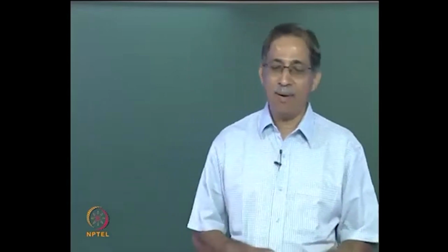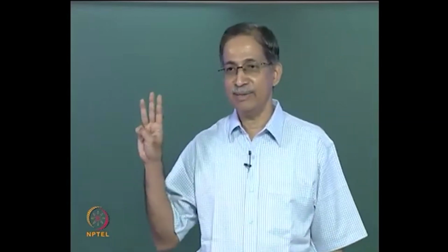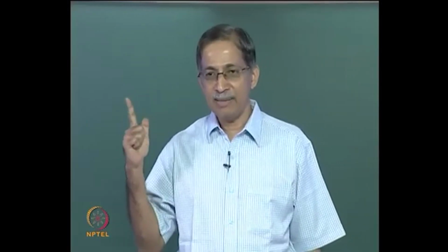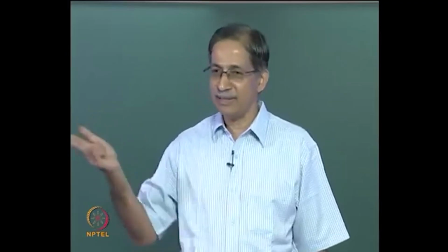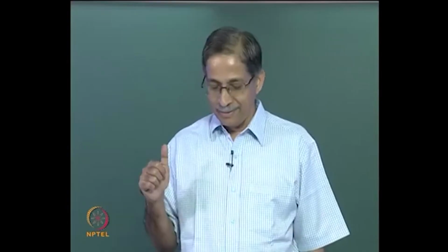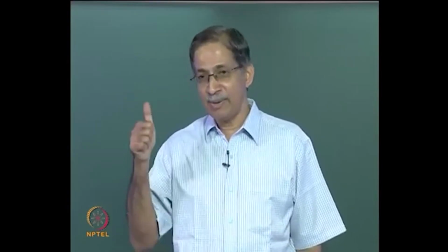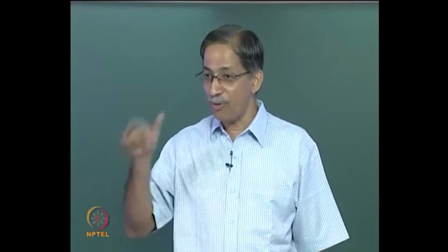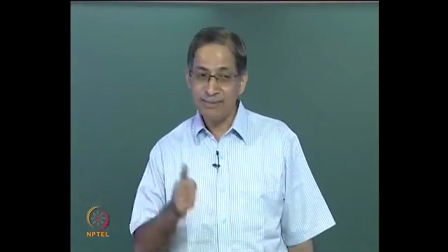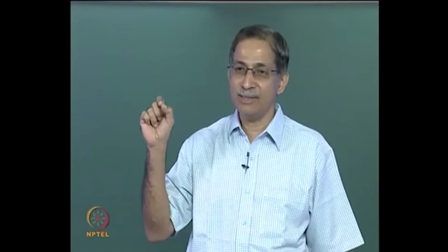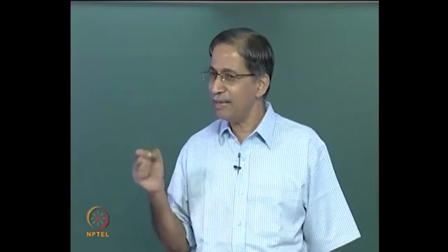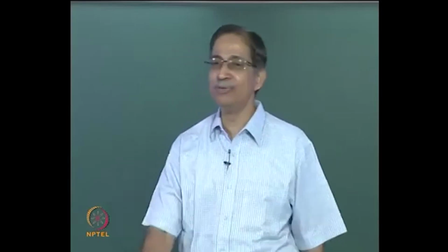You remember all structures have to satisfy 3 requirements. What are the 3 requirements? Equilibrium, compatibility, and force displacement relationships, which include stress strain relationships, constitutive relationships. Statically indeterminate structures, equilibrium alone cannot help you get the unknown forces, you are forced to look into the other 2. Statically determinate, you are getting away with just looking at equilibrium. The question arises, a good student should ask this question, does it mean somehow automatically compatibility is satisfied? Yes, prove it. So the contra gradient principle actually proves it.